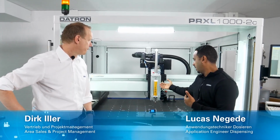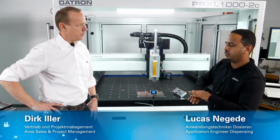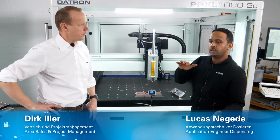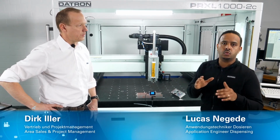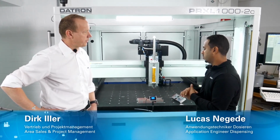And we have double heads, two heads with two different kinds of material, or the same material with a double head. There are additional equipments too: if you are not using cartridges for material supply, pail pumps can be used for pail material supply from 20 kilograms up to 200 kilograms, and several kinds of cartridge systems or supply units can be adapted to the machine.